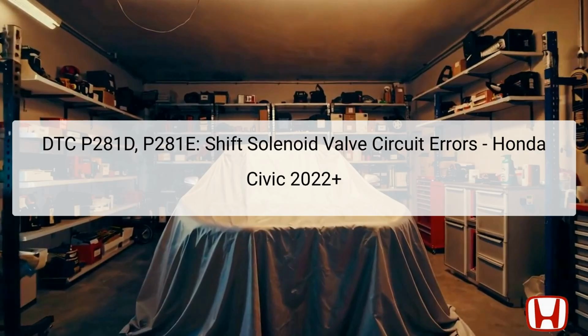The shift solenoid valve plays a crucial role in controlling the flow of transmission fluid, thereby affecting gear shifting. It is located within the transmission assembly and can be accessed through the transmission fluid pan. The TCM, which is responsible for altering the engine's and transmission's behavior based on input, determines whether there is an abnormality based on the signals it receives. Diagnosing these DTCs accurately will help in ensuring the smooth operation and longevity of the vehicle's transmission system.